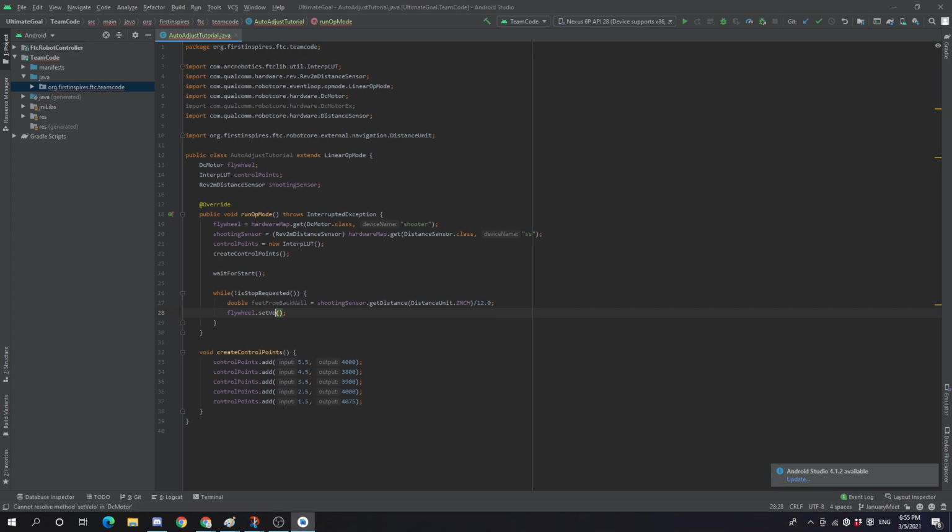And well, since it's velocity, I have it set up as a regular motor, right? So since these are velocities, you can essentially use the setVelocity method. Actually, we can do that right now. So if I change this to a DcMotorEx, and I do this here as well, you can see now we get access to a bunch of more methods that allow us to better control the shooter. So say we want to set velocity, and I'm just assuming it's a 1-to-1 bare motor.